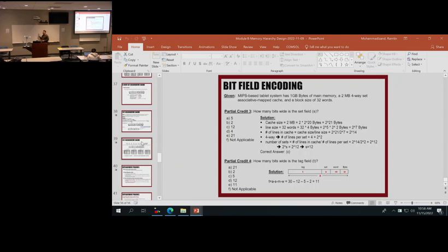So if you look at the transistors, the number of transistors that you can use in decoders are used with different switches, transmission gates, and so on. And if you look at how many transistors you need for example, a 2 to the 32 decoder of that type is thousands of transistors. So that's why breaking them into smaller pieces is going to be more efficient. Having this kind of hierarchical addressing is going to be better.